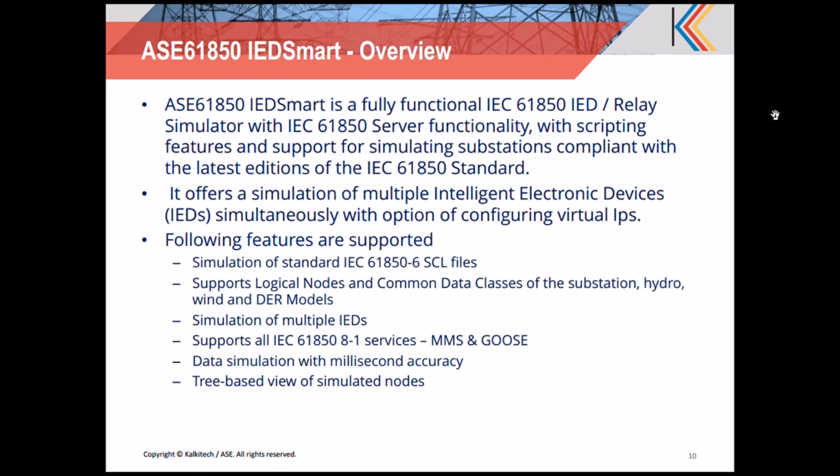Okay, after the SCL Manager demo, we are moving on to IED Smart. So IED Smart is a simulation tool. After the SCD file is created by the engineering tool, the same SCD file can be simulated in the lab to have multiple IEDs simulated in the lab with virtual IPs. So that is done by the IED Smart tool.